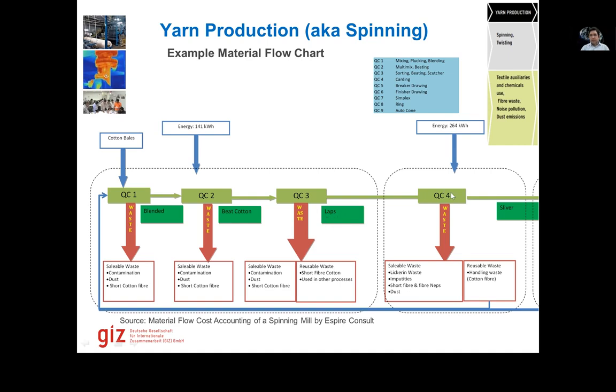And then in the carding process, we put them in the machine and we start drawing them very slowly, so they start taking the shape of a tube or a rope. We don't call it rope because it's not twisted. It's like a non-woven tube that is coming out, which is called sliver. And here again, it is purely energy.